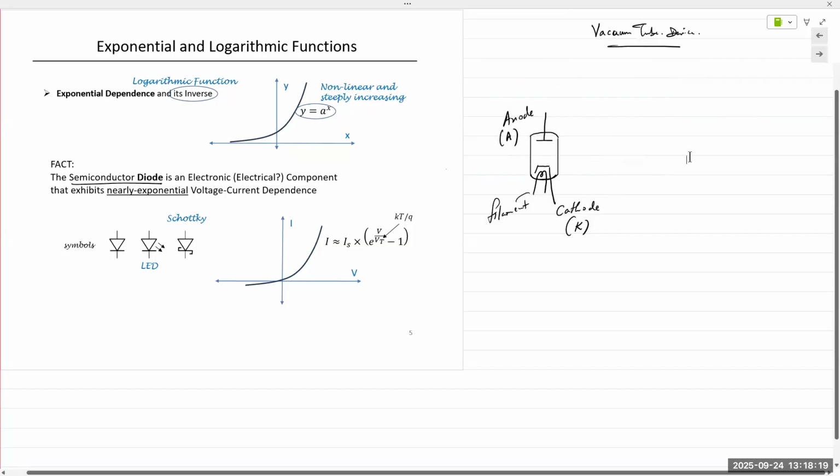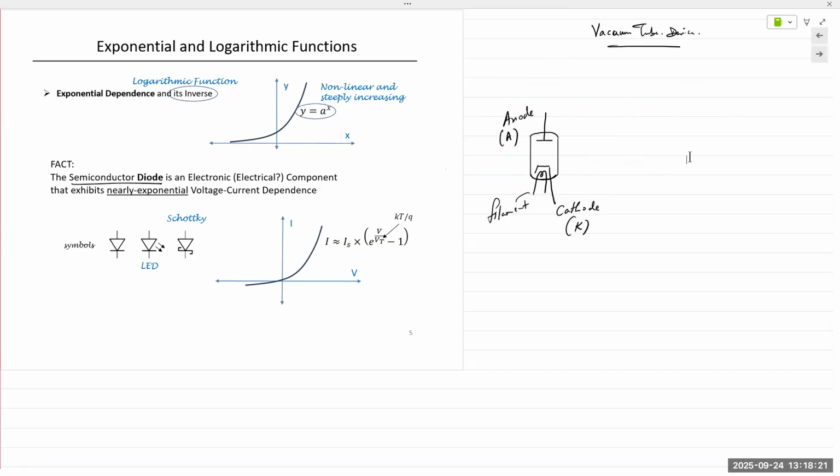When it reaches a certain temperature, depending on the make, model, and the material that's used to construct that electrode, they start emitting electrons, and they kind of float on top of the surface of the cathode. They impart enough energy to the atoms of the cathode that there are electrons that come up and float on top of the surface. They are now free to move.